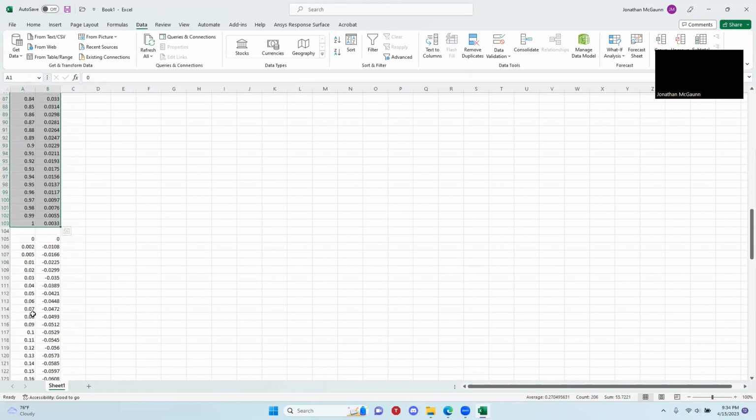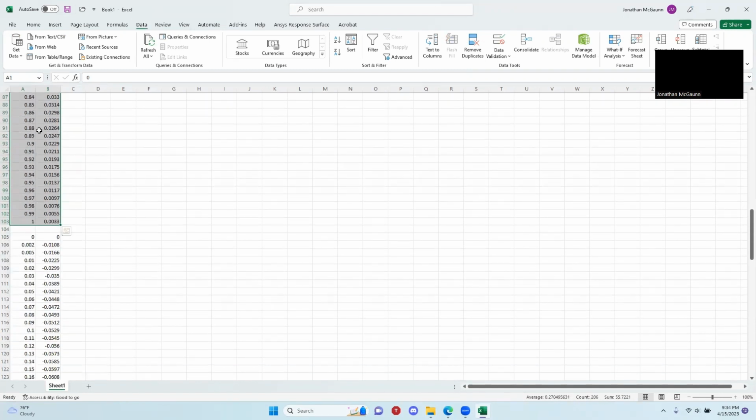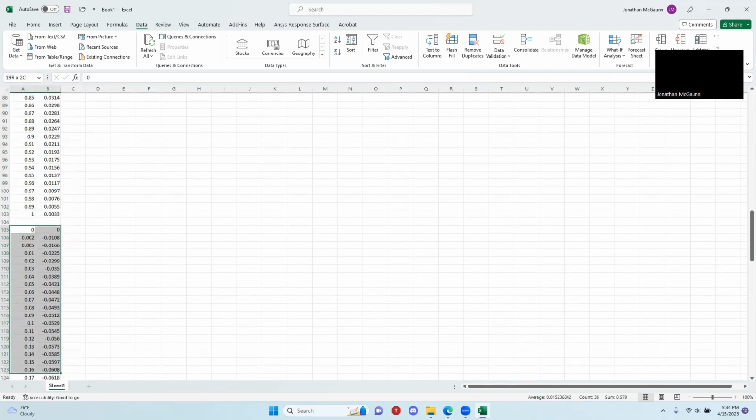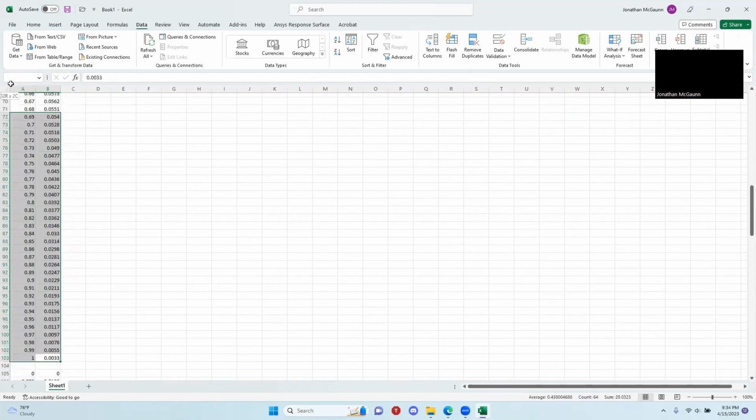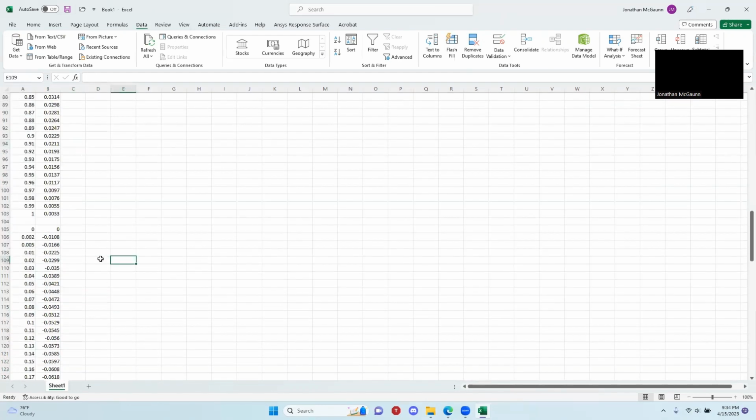Again, each of these coordinate files is a little bit different. But this is the upper surface, and then you'll see it jumps all of a sudden and goes from leading edge to trailing edge of the lower surface. SolidWorks needs to read a continuous smooth line for it to be accurate. In some cases, you might need to separate the upper and lower surface, and for that you can load these coordinates in separately with the method I'm going to show momentarily. But if you want that smooth curve, it's ideal that you order them in that smooth manner.